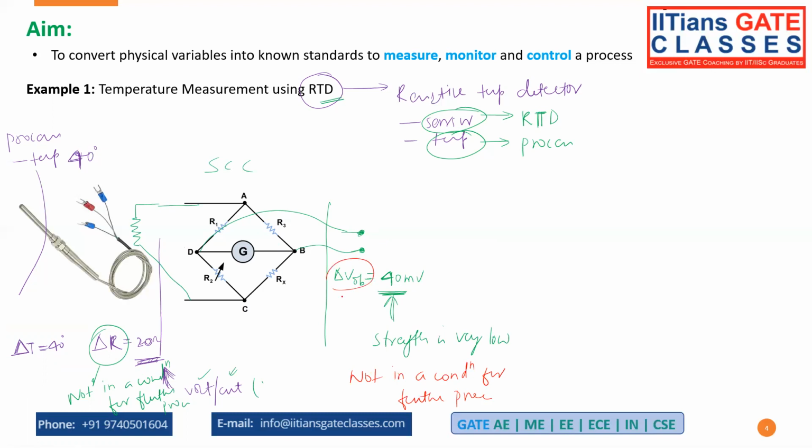Now you have got a voltage quantity. Again, you don't want to change into some other quantity, but you want to increase the strength. So you will place an op-amp or amplifier circuit to increase its strength, right? So we have used an op-amp here. The connection is not shown, just for understanding we have used a block diagram. Let's say the gain is 10 or 100, so it will increase its strength to 0.4 volt or 4 volt, depending on the gain and the V plus and V minus, right? So let's say here we got 4 volt.